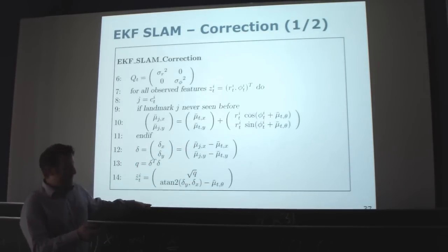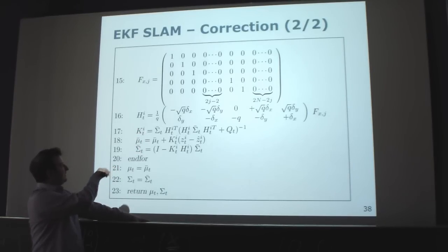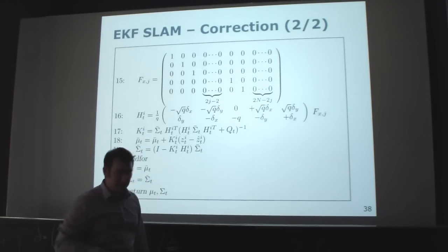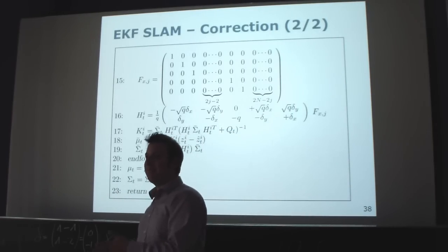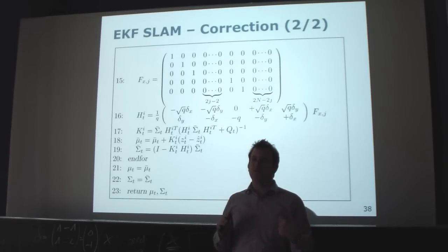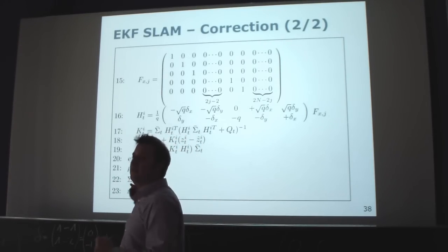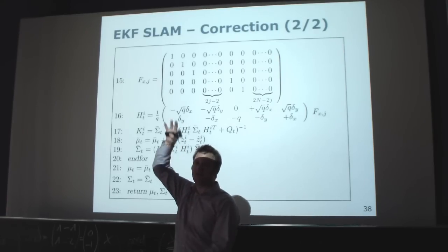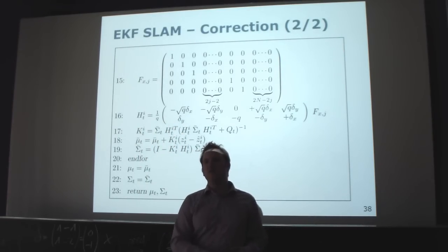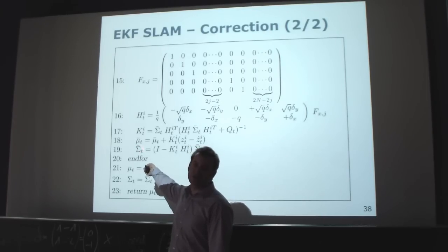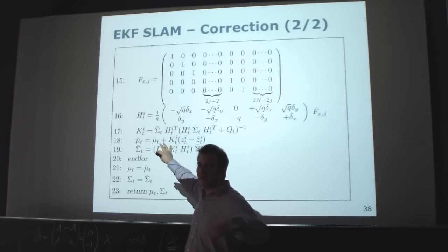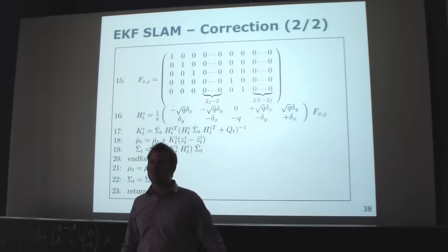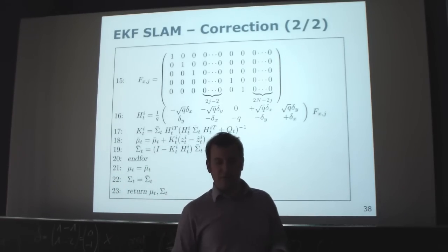The problem I have, however, is that I have to make this update of the mean and the Kalman gain, updating the mean and the covariance, at every point in time, so it's quadratic. So in one case I just have to do it once, and in the other I have to do it I times. So in one case the inversion is more expensive and the update is cheaper, and in the other the other way around. So it simply depends on the dimensionality I have. If I'm typically doing this in the context of SLAM, it's actually better to stack all those matrices together, invert it once, and then do the update, because typically n can be pretty huge, so the dimensionality of this matrix may be large. But sometimes it's easier to understand if I do one observation at a time, and not all observations at the same point in time. So there are two ways of doing this.